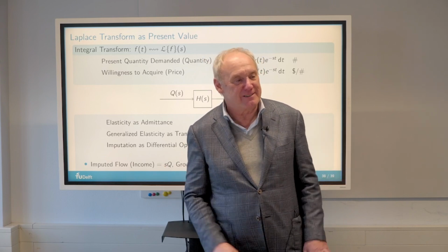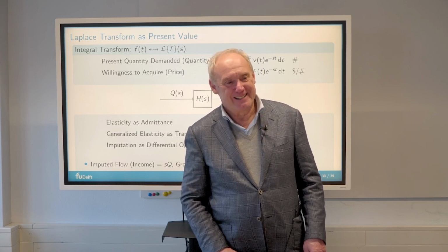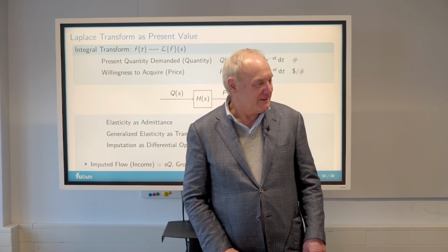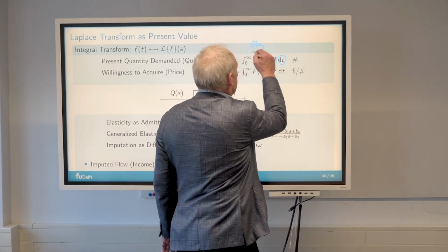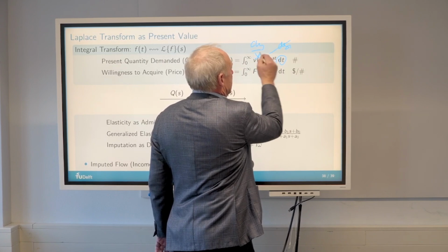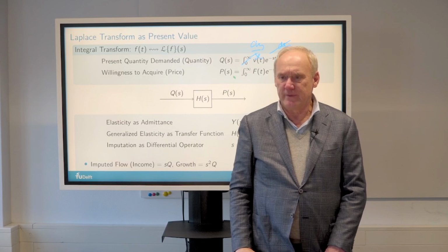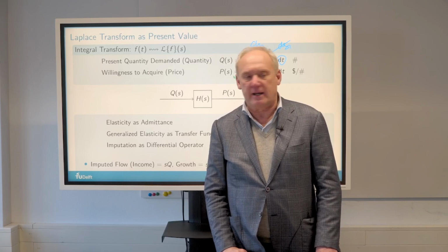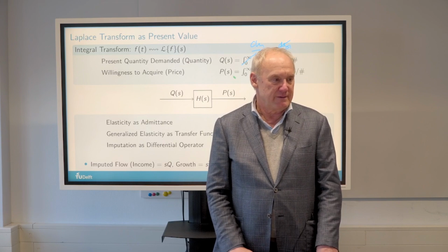What are the units of that? Is that also amperes? That's my question. Is that the case? Yeah, you won't get amperes. So that's very good, you get charge. Because you integrate over time. If this is charge per second, and this is d seconds, then these will cancel, and this will be charge. Okay? So the Laplace transform of a variable does not have the same units as the variable itself. That's obvious.